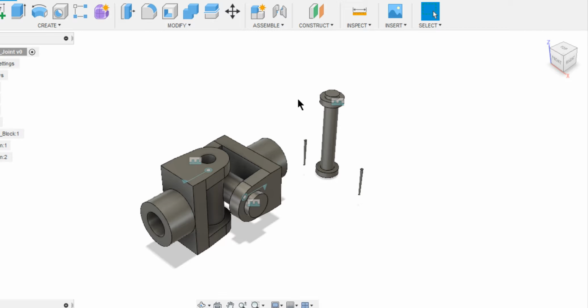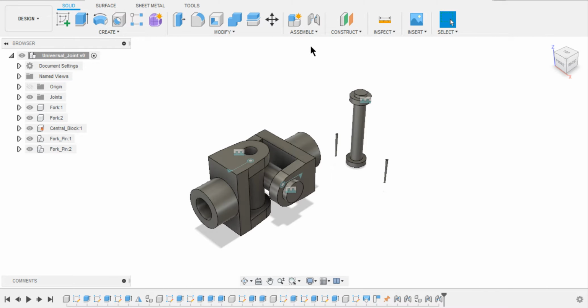If you observe here, the collar for the duplicate fork joined to the fork pin. This is because we simply pasted it. In order to avoid this, we have to perform paste new. For now, I'm satisfied with it and it saved me a lot of time.